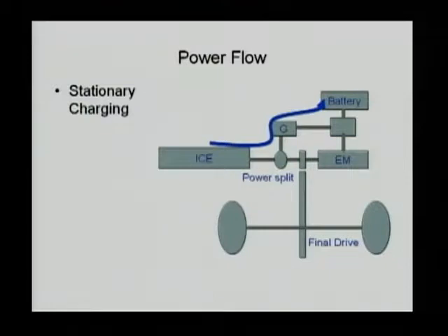One thing you should be aware of is that in many of the hybrid vehicle systems, there's no alternator. There's no small generator that can charge the 12 volts battery or the 14 volts battery in the vehicle system. However, you still need that 14 volts battery for many of the auxiliary equipment, such as your wipers, door locks, powered seat, headlights, tail lights. All of them are going to need power. That power is coming from the 14 volts battery, and that 14 volts battery needs to be charged.